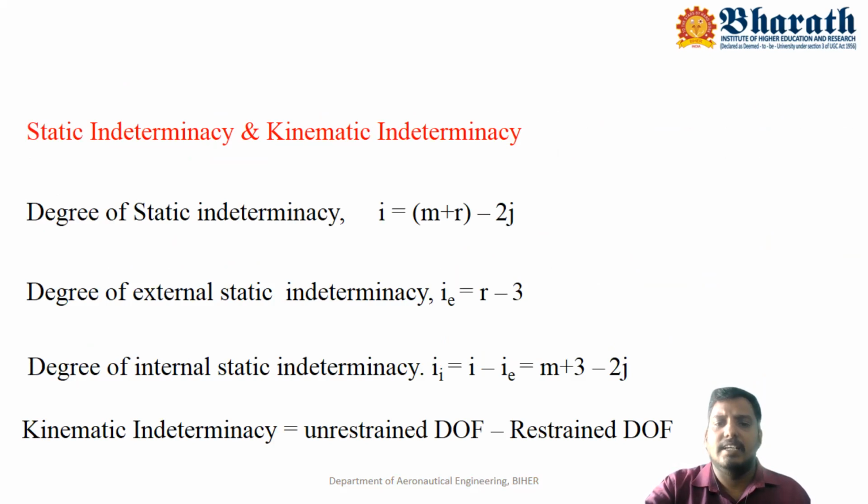If it is a statically determinate structure, it means all the internal forces induced in the members as well as the reactive forces from the supports can be analyzed with the help of static equilibrium equations alone. Then this structure is called a statically determinate structure. If it is a statically indeterminate structure, it means that, in addition to the static equilibrium equations, you have to develop stress-strain compatibility equations to analyze the internal forces induced in the members as well as the reactive forces from the supports.